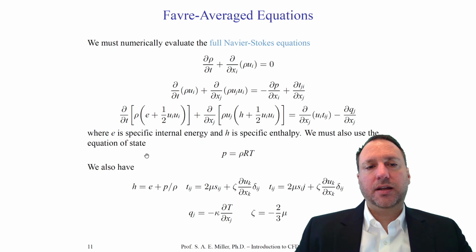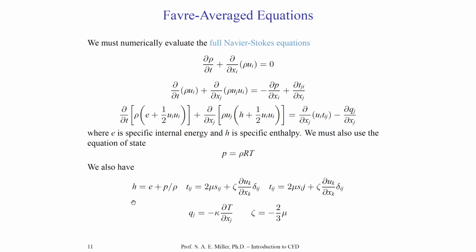And the third is an energy equation for, of course, an internal energy with a kinetic energy. Here, E is the specific internal energy, and we've introduced H as the specific enthalpy. Let's close this equation with, of course, the perfect gas law, P equals rho RT. Then we can define the rest of the variables for this particular set of equations. I've written this particular equation twice. Please scratch it in your notes.